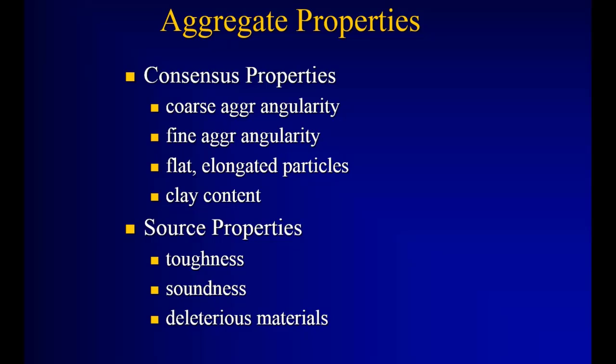So that's what North Dakota did. South Dakota, prior to Superpave, I did an aggregate class and mixed testing class here last week here in Pierre down at the DOT lab, and what they did prior to this fine aggregate angularity requirement was they specified the minimum amount of what they called manufactured fines. And a manufactured fines was a man-made definition, was if there's 3 basically quarry types in South Dakota, which you'll see in a photo up here.